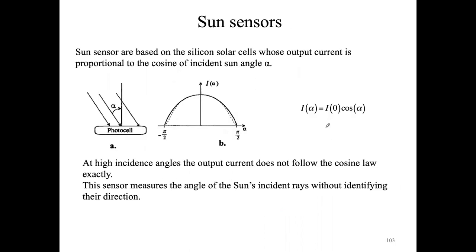So to conclude the part on the attitude determination, we have to discuss briefly the sun sensors. Briefly, because the concept behind the sun sensors is really simple compared to other sensors. The main concept is that we look at the sun and use its known position knowledge in order to determine basically the vector W from the sensor and compare it with our a priori knowledge V.